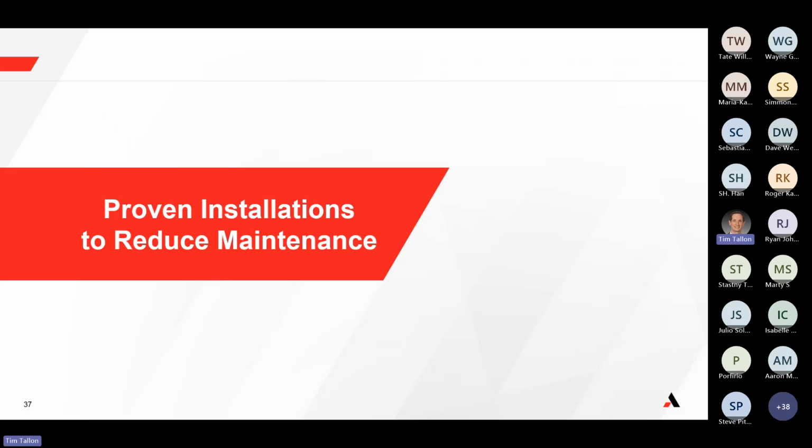So now I'd like to switch gears. Those are some of the practical configurations for an analyzer in a high particulate case. How do you choose the analyzer? Well, it really depends on the particulate loading, and on what measurements you want to make. It also depends on whether it's sticky or abrasive, or saturated, or any of those considerations.